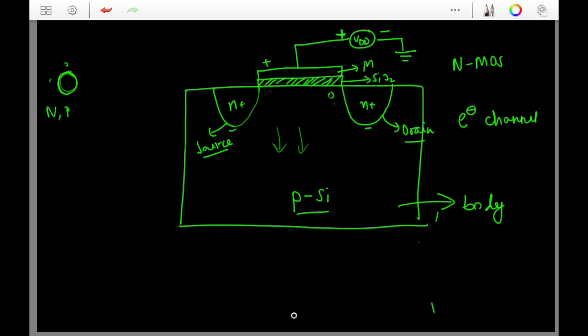These have 3 electrons. They want a 4th one, so they take an extra electron from the semiconductor and leave a hole in place. So these are basically negative ions. When the holes move in this direction, they leave negative ions over here. But this still doesn't answer the question. These ions are practically immovable. They cannot move. So where are the electrons that I talked about?